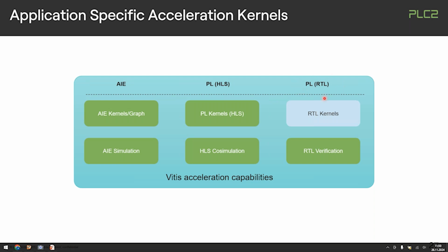You can incorporate RTL code as it is, as long as it adheres to the XRT level control registers that it needs. It's maybe like 8 registers or something, depending on your interfaces. You have the HLS tool flow that can directly pick from your C code and map it out into HDL. That can be guided to create such XRT level interfaces. And the AI engine is a very specific compiler that needs to create configuration data for this new IP that you have in there. And this is also aware of XRT control in a certain way. So that's what we have.